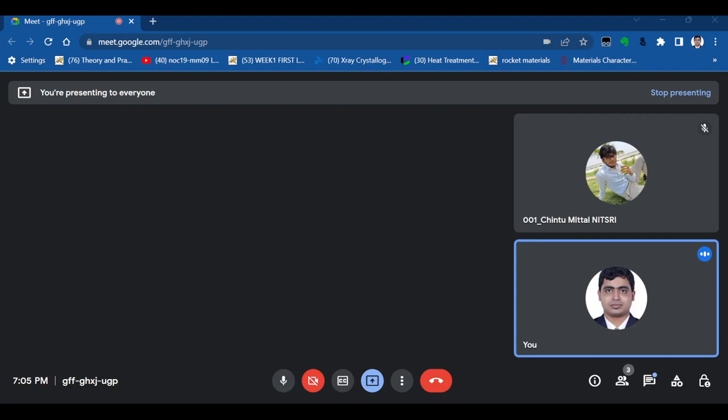Sir, B. How? So the dot product of a dislocation and plane is zero. So one bar one zero is the dislocation and one is the plane. When we take the dot product, it will be zero. No, no. First, read the question properly. On which plane do these two partial dislocations lie? So you have to consider the right side two partials, not the left side one, a by 2, 1 bar 1 0.